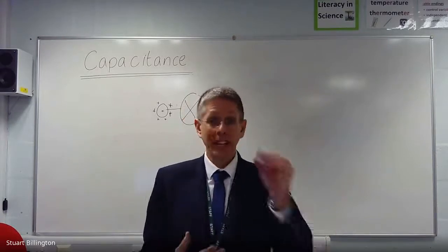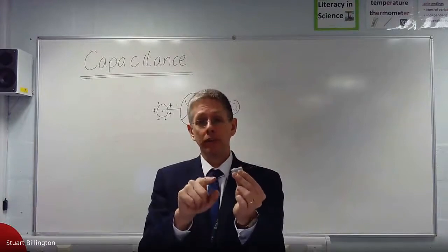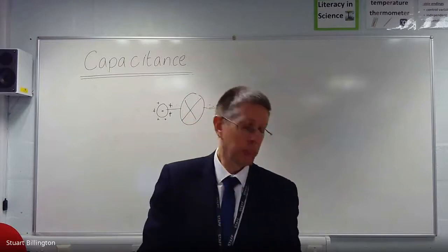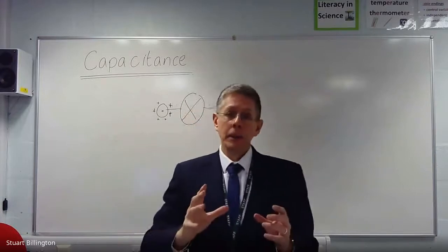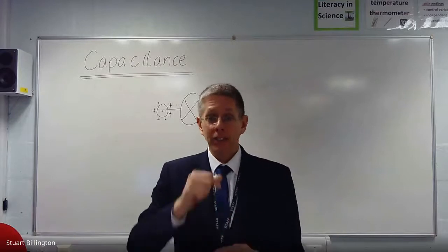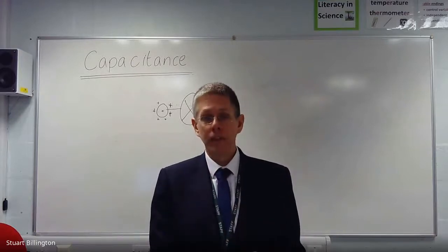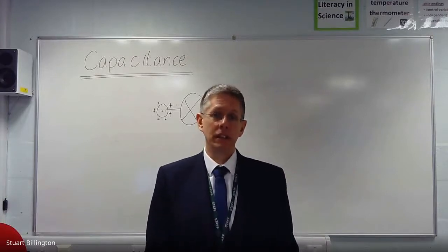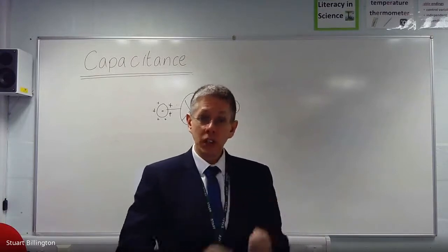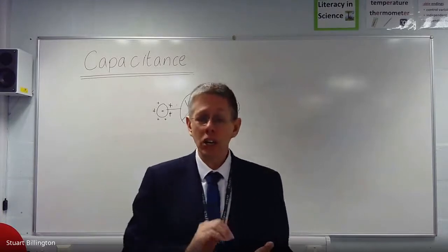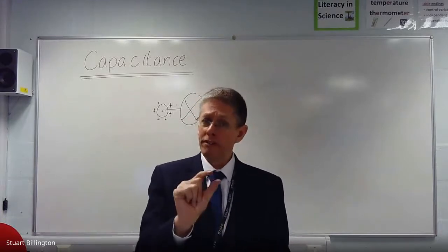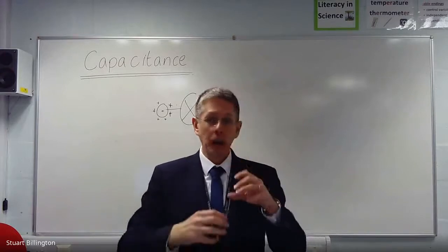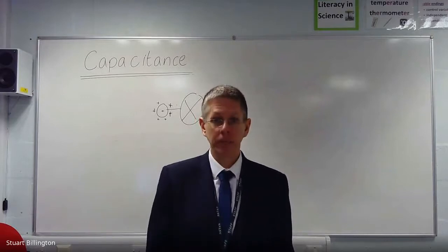The other end of it is very, very negative. And that means that if we connect it in a circuit, charge will flow from one side to the other side around the external circuit. It's a little bit like a chemical cell. It doesn't have the capacity to recharge itself, but it's got very, very little internal resistance. Therefore, when charge does flow from the capacitor, you can get incredibly high currents, albeit for a very short amount of time. It has other things going for it as well, but capacitors do have that advantage.